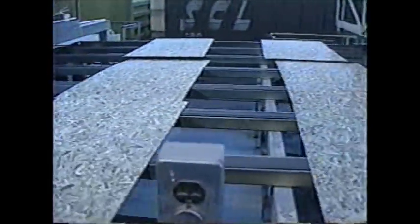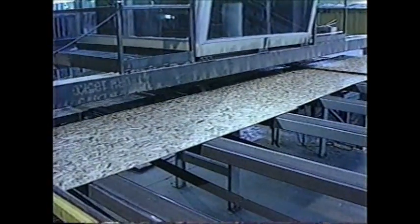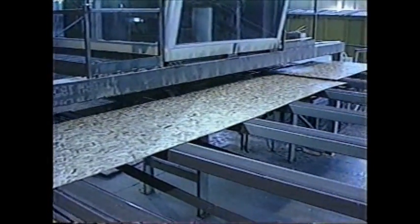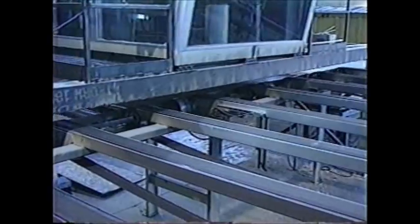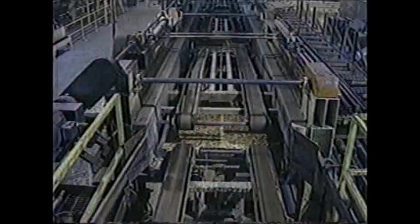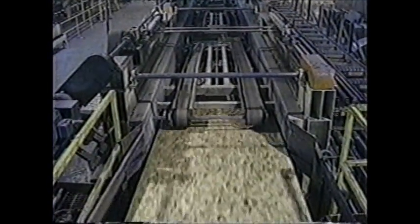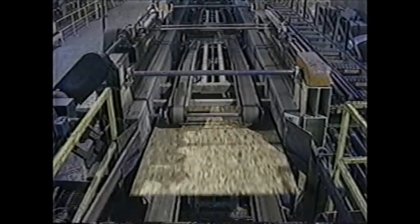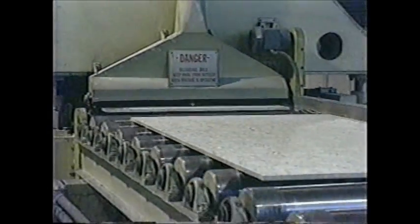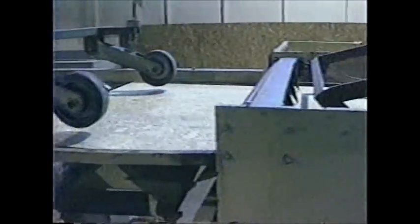The panels are graded immediately after sawing from a grading station above the conveyor. The grader watches for surface damage and defects, defective material, broken edges, and corners. Panels are routed to appropriate bins and separated according to grade. After separation by grade, panels are sanded and, if required, edges are machined.